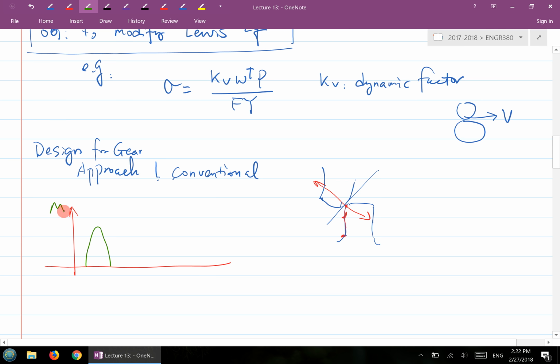So what you would say in this particular case is, you probably will see here is basically the bending moment, starting at 0, and then here is your MA. So basically, you will see that gear 2 experiences a bending moment from 0 to a certain magnitude MA, and then comes back to 0 like this. It's basically a repeated type of loading. And for this particular one, you may have a mean value here. So that's the loading condition for the gear 2 study here.